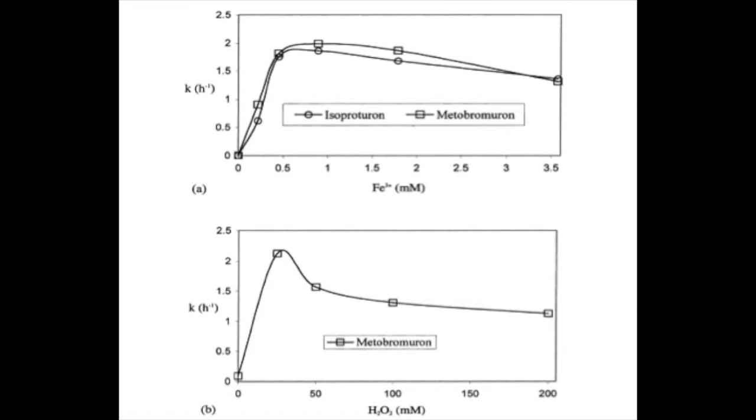It's important for the efficiency of the Fenton process that you have optimal concentrations of your reactants. Now these vary by the substance being degraded, but for phenolic compounds, the iron 3+ concentration is found to be best when it's around 0.5 millimoles per liter, and for the same reaction it is best when hydrogen peroxide is around 21.22 millimoles per liter as well.